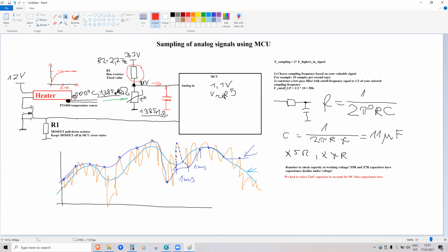So maybe the electricity jumps or falls a little bit at the input, or the same effect would happen if the microcontroller's power supply made a short dip or short spike, because the voltage reference is connected to the power supply through some circuitry.